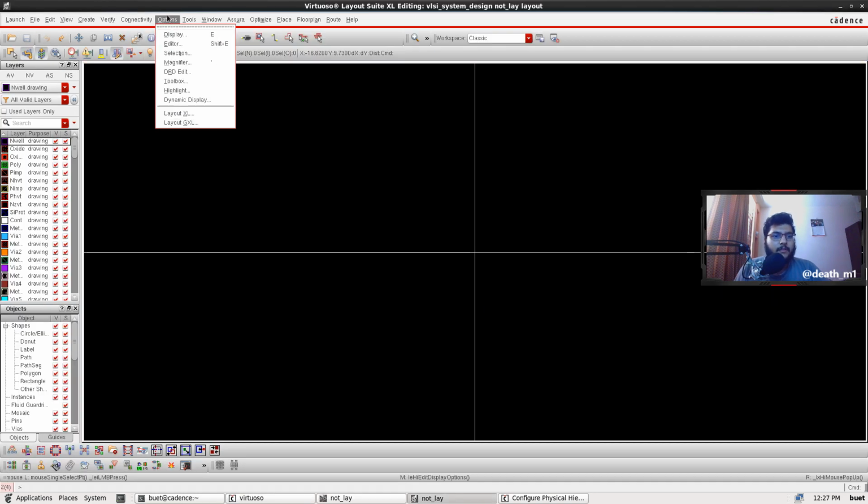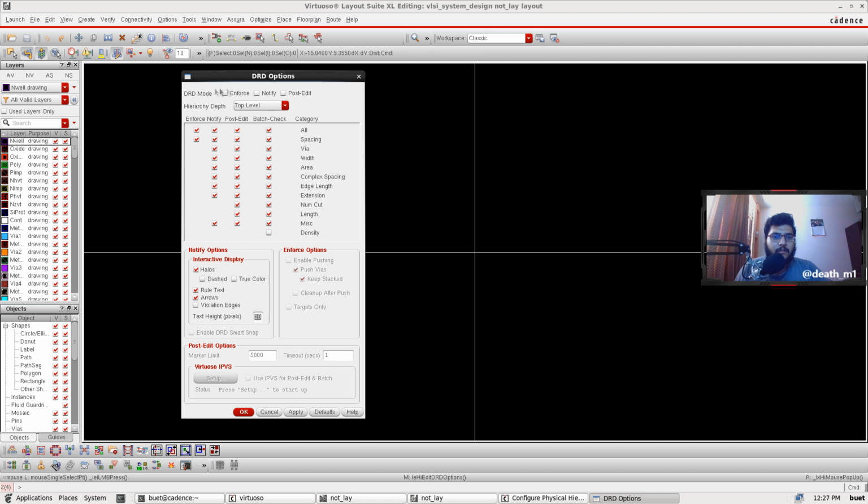Okay, so now you have to go to DRC edit and hit notify over here and press apply. You might get one more option here, three tick options. You have 3 check boxes. You have to basically set notify over there as well, then apply.